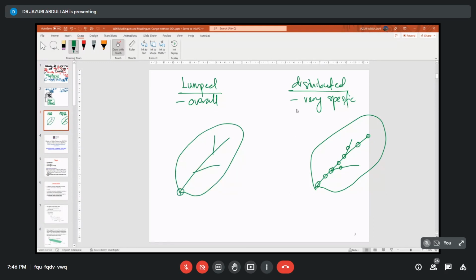So as compared to the distributed, you can have several locations where you can get what is the Q versus time. Okay, so this is what you call it as the hydrograph. But for the LAM model, basically this is only one outlet with one hydrograph. Okay, so basically this only that you can get the hydrograph here.